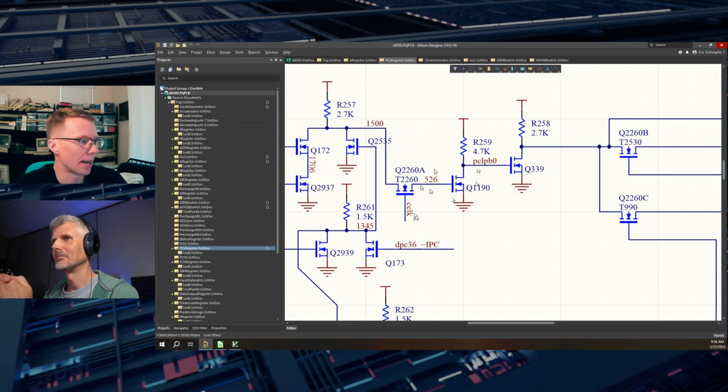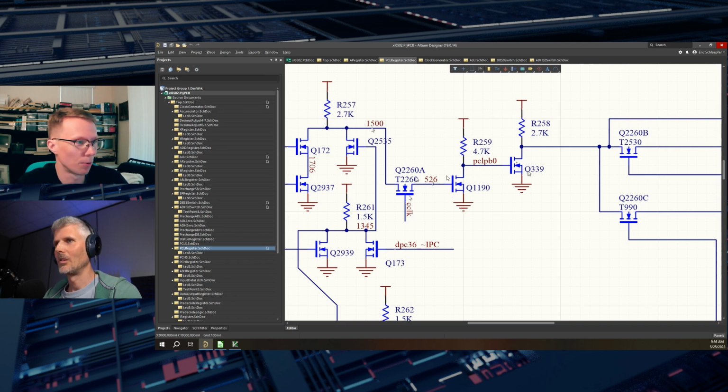And what happens is that when we're in the C clock phase, this transmission gate is turned on. And so whatever data is coming from the output of this gate beforehand comes through and then gets loaded into the gate of that buffer, right? So the buffer now has either a 1 or 0, either high voltage or 0 volts loaded into it.